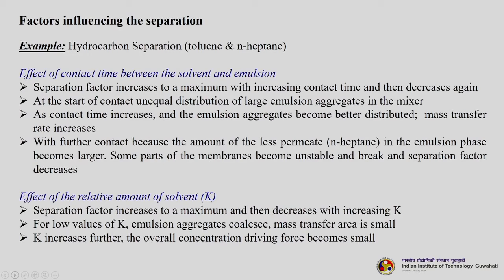So for example, hydrocarbon separation, toluene and N-heptane. Based on this particular example, it is discussed how the different factors are influencing the separation. So, effect of contact time between the solvent and emulsion. In any separation, or any mass transfer that is happening, or even reaction that is happening, contact time is extremely important. So contact time should be optimized, it should not be too less, it should not be too high, okay, there should be some optimized value, which needs to be found out by doing different experiments.